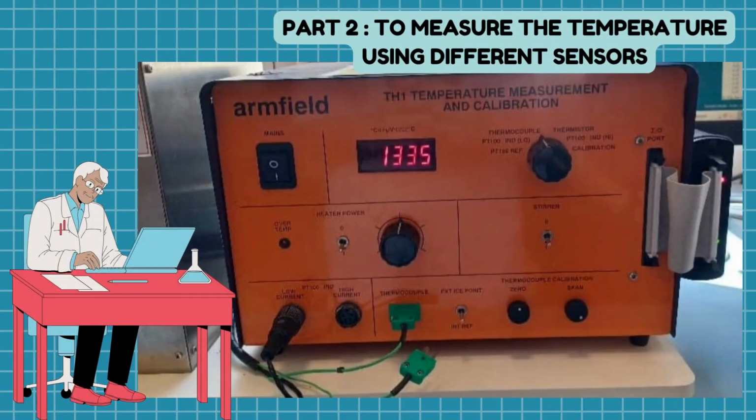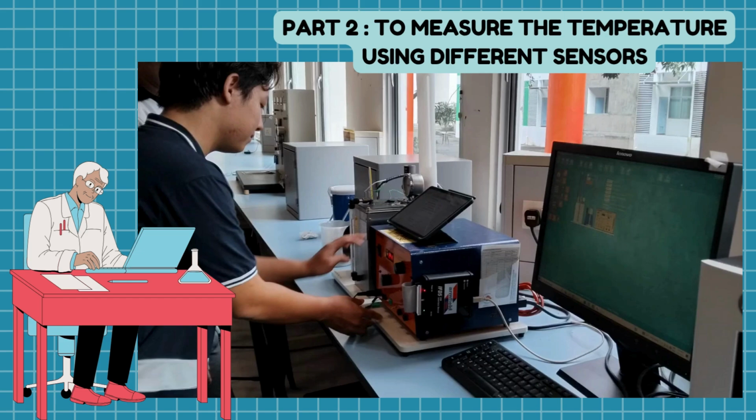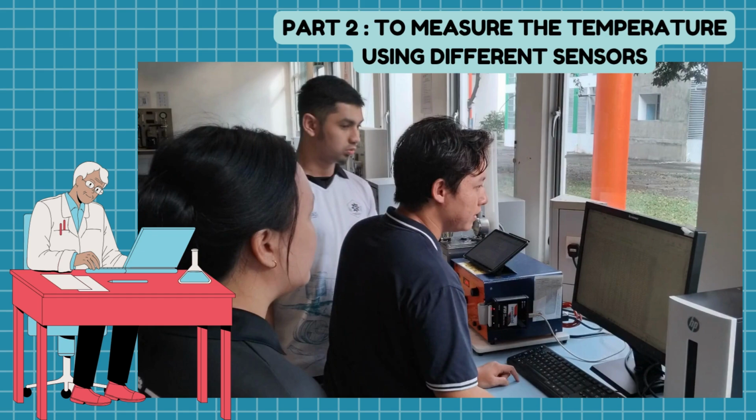First, set up the temperature sensors like thermocouple, RTD and thermistor according to the manufacturer guidelines and ensure proper thermal contact. And then, connect each sensor to a digital multimeter or data logger. The third step is to immerse the sensors in the temperature medium. Example, a hot water bath or heating plate.